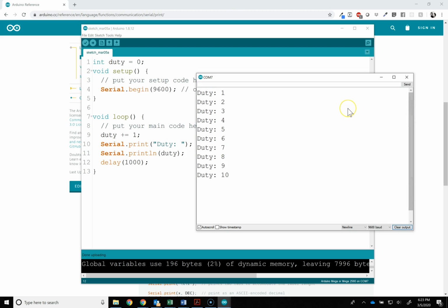This could be very valuable for your code as you're working on the lab for this week, where you're doing exactly the same thing. If you're ever having issues where you're not seeing the results you're expecting, you can use the serial monitor to display the output of what's happening with your code and your Arduino as you're doing it. This is always one way to work at debugging your Arduino code. The other way is to look at the signals coming out of your Arduino. We can do that with some tools we're going to get into in the next couple weeks, using the oscilloscope as well as the digital multimeter.